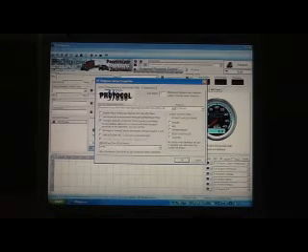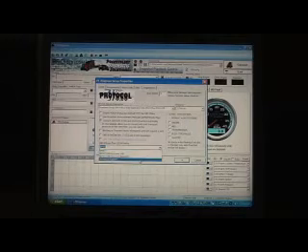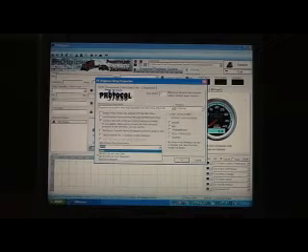And then here you have your OBD2 pass-through J2534 device. This is the same adapter in many cases as will be used up here. However, you must select that adapter here as well. Now, we are using a DPA-4 Plus. A DPA-4 Plus does not support OBD2, therefore it is not listed here. So we will select a DPA-5 and move to OBD2 demonstrations a little bit later on.